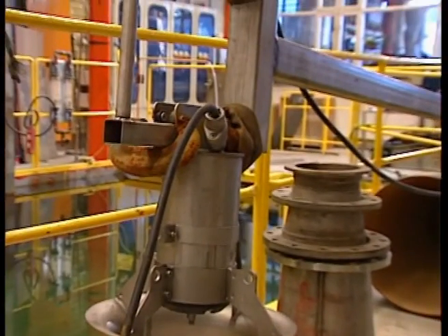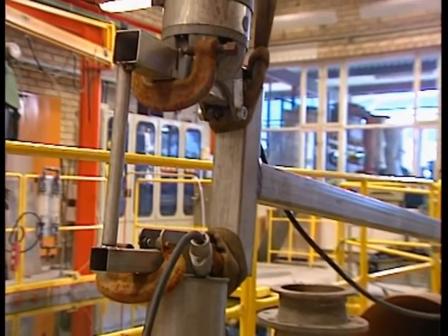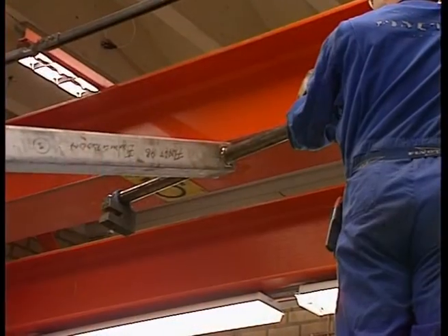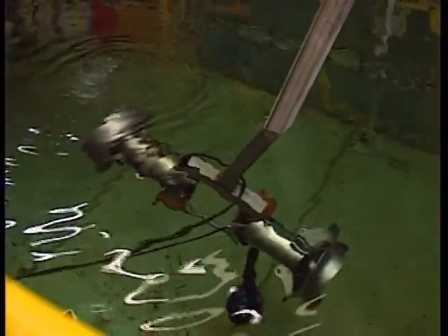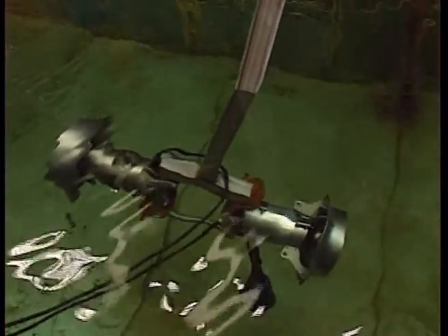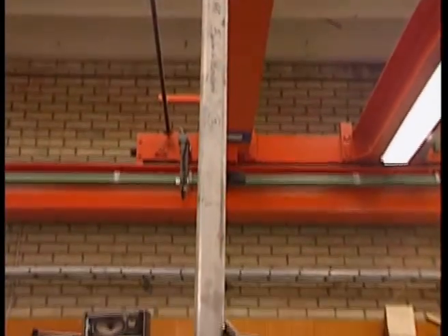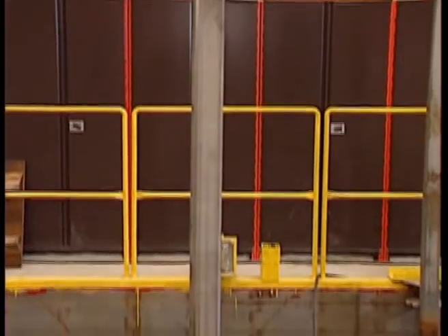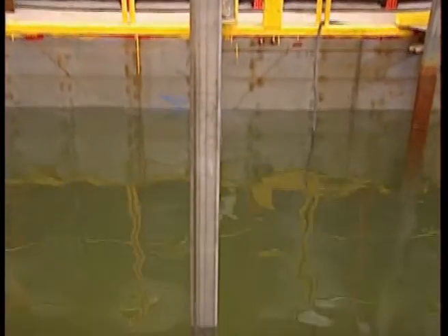To visualize this in another way, we have constructed a test rig in our laboratory. What we have here is simply an articulated swing. The swing is fixed to an overhead crane above the test tank. At the lower end of the swing, two agitators are mounted. You will note that they are working in opposite directions. The agitator having the larger thrust will win this battle, deflecting the swing over to the opposite side. The agitators are connected to power meters, so we can check their power consumption while they are running.